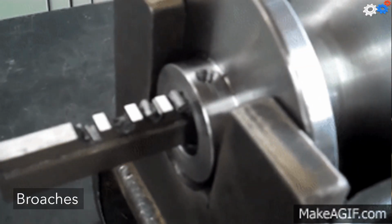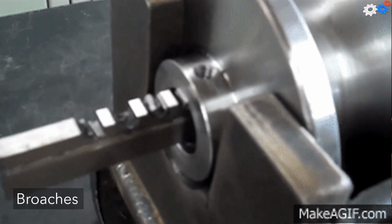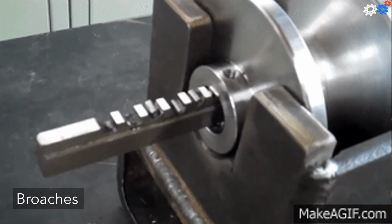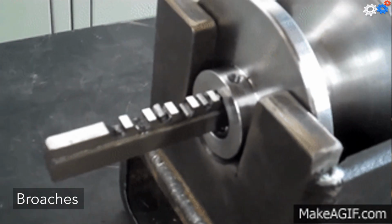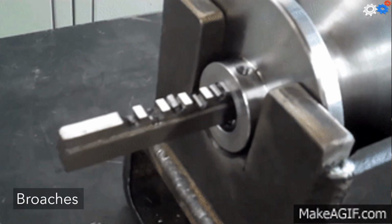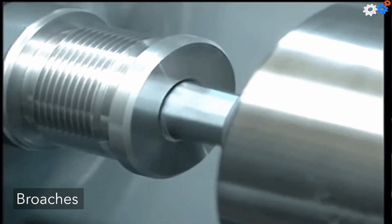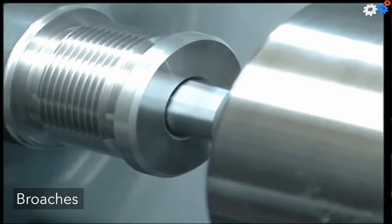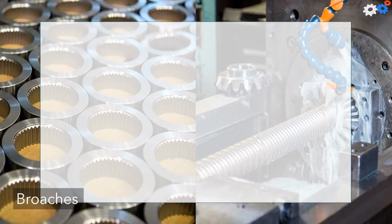Owing to its complex geometry and the low speed used in broaching, most of the broaches are made of high-speed steel. But in broaching of certain cast irons, the cutting edges are cemented carbide inserts, either brazed or mechanically held in place for the broaching tool. Broaching is the only traditional method of machining process that can cut a non-circular hole or a pocket with 90 degree corners.